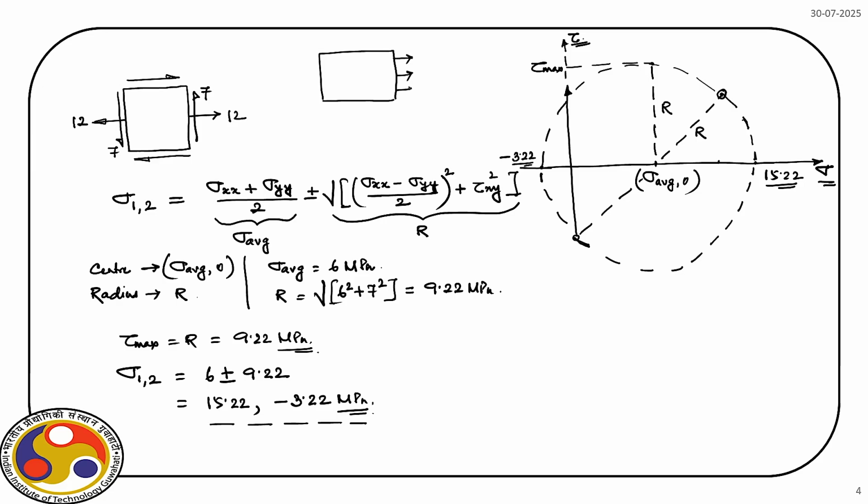So, if you have all in-plane loading, then we end up with this type of problem, and we derived the expressions for stresses and their maxima. So, this is a case of plane stress, right. And today we have solved an example, and we have drawn the Mohr circle also. So, you can completely solve this problem.